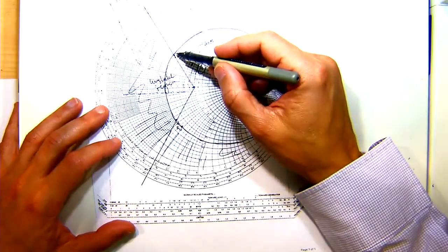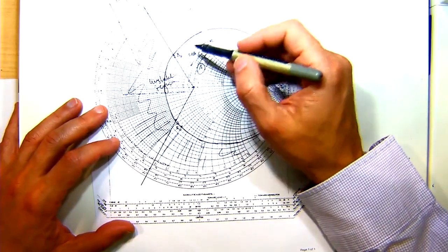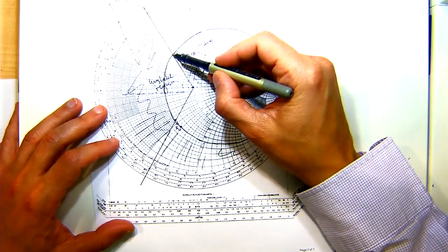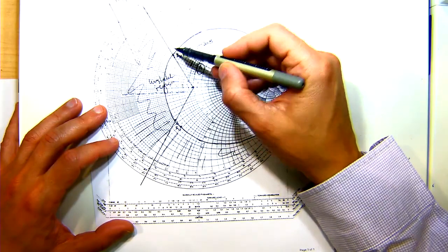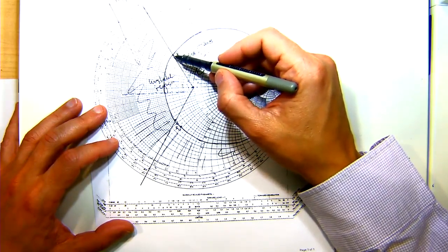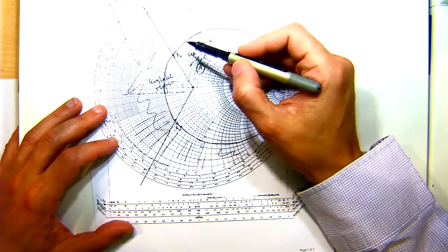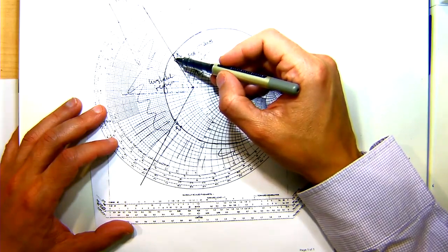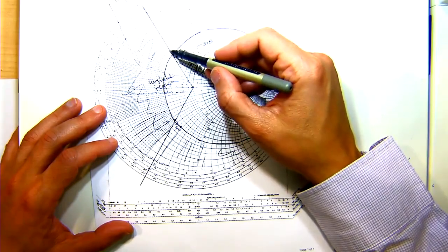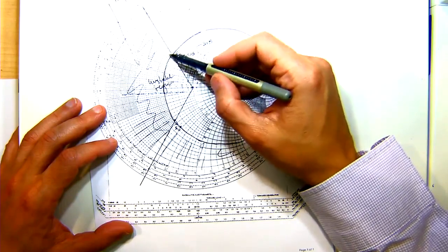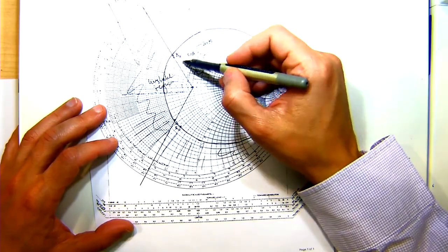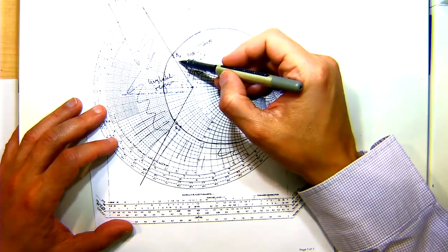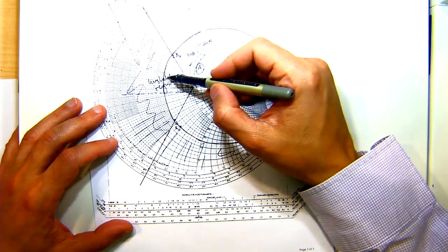But what I'm saying here is if GS is equal to 5dB, this is the most stable point, and at this particular point where you get the maximal stable gain, you wouldn't design it there, because with a small perturbation, you get the resistance a little bit wrong, and you get into a different region, which will make you unstable. That's why you would never design it around this point. So what you would do is choose less than the maximum gain, less than the critical gain.